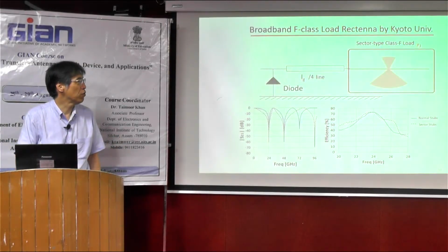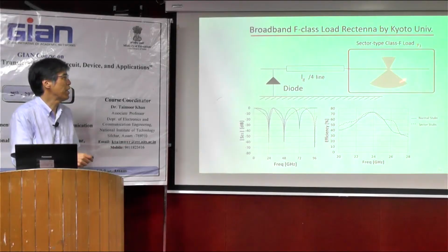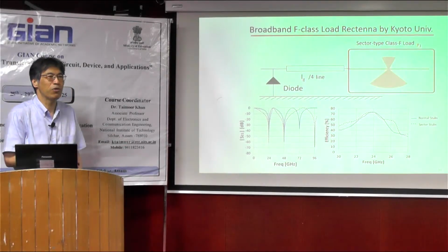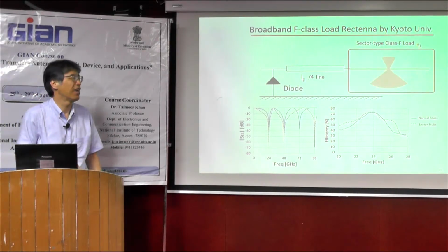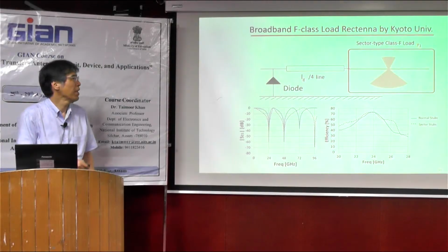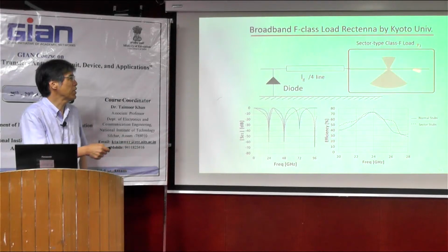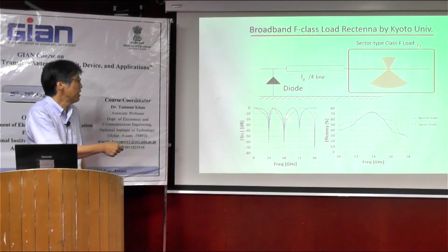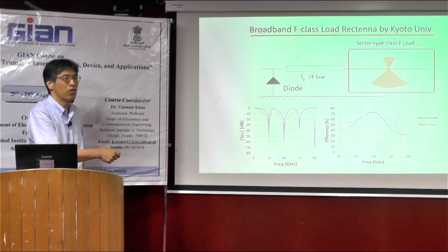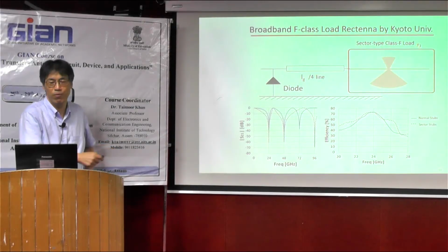And we, Kyoto University, developed a broadband matching circuit at the output filter. We would like to develop the output filter, and it's a very simple sector type class F load. And as a result of this broadband matching circuit, we can expand the bandwidth of the rectifier, for example.